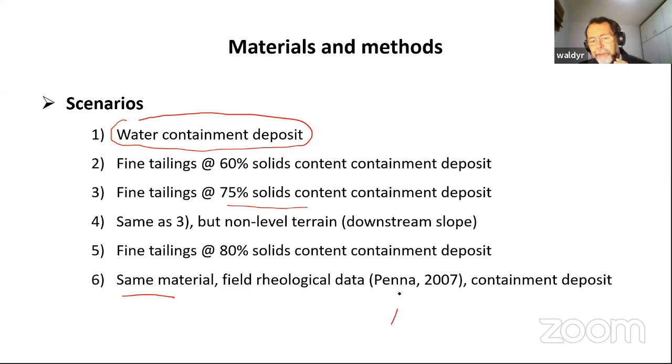I have presented to you that small scale field test, remember, with the 4 centimeters. So this former student has done measurements there, and then we use the undrained shear strength that is in kPa, but for rheologists it's the same as what we call yield stress. So for the rheology, you have the yield stress, it's the same idea.